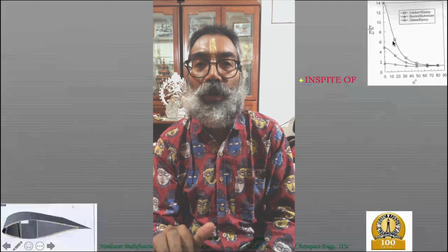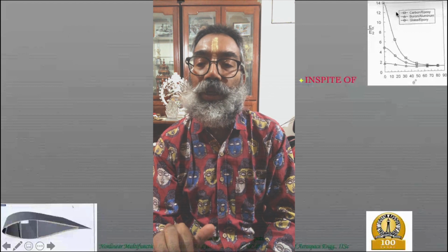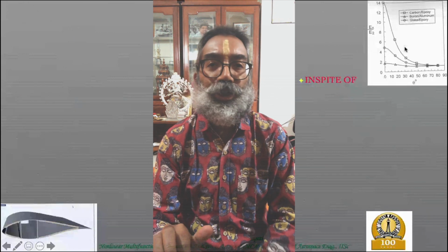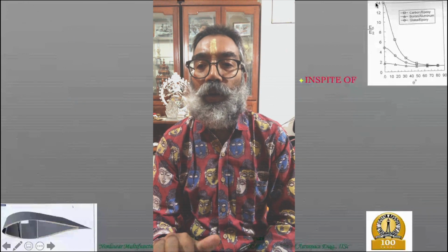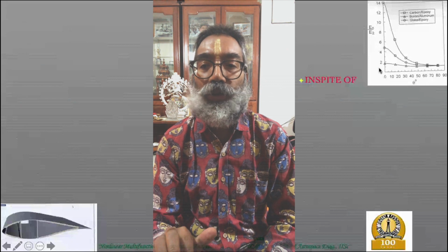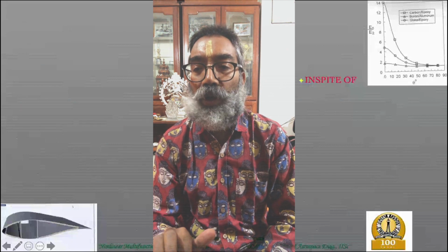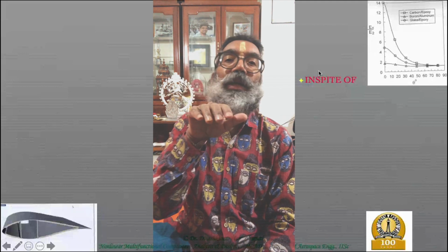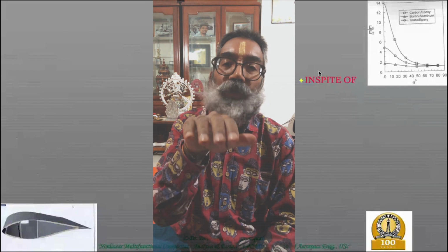That is basically unity at 90 degrees. In between, what happens is there is a monotonic drop in the stiffness value, and this is the situation with the strength as well. Whatever large strength you have in the longitudinal direction, that drops off as you go towards the 90-degree direction. So this is one of the issues if you are using just all the fibers in one